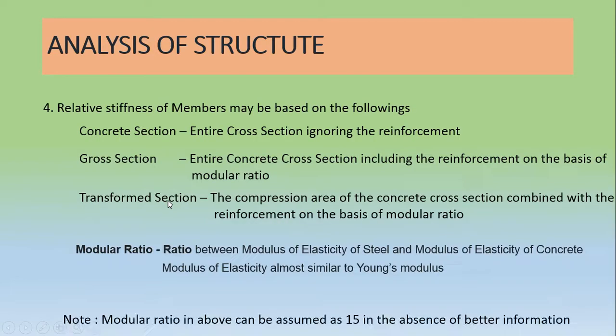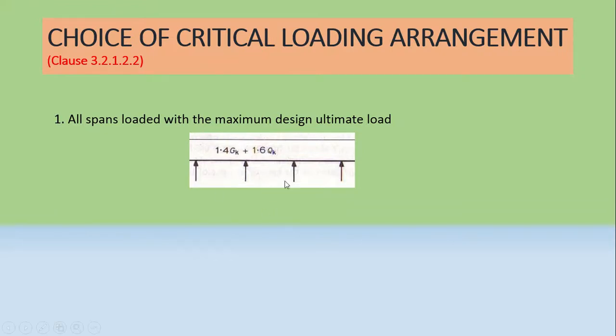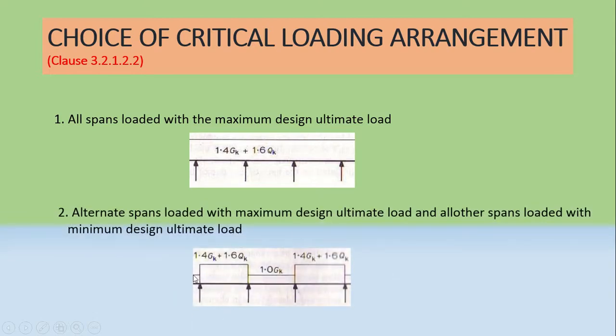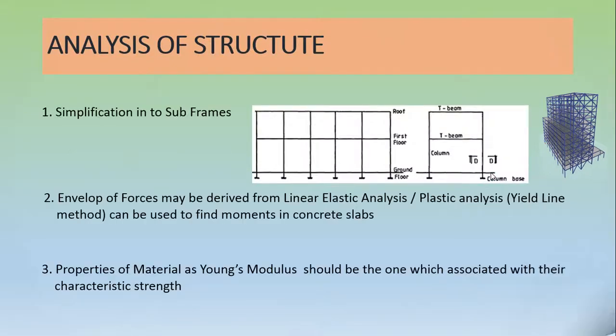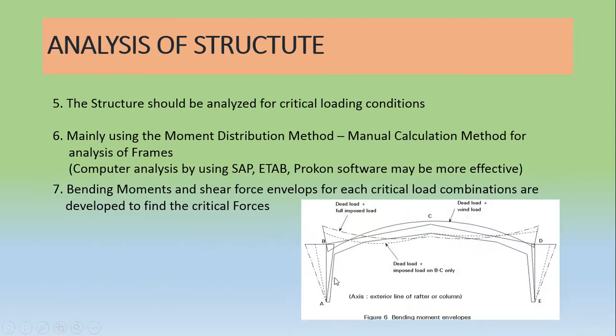Earlier I showed you this beam, and we can draw a bending moment diagram on the same beam, and for another load combination you can draw another bending moment diagram on the same beam section. So here we consider this frame. Let's think that one bending moment diagram is where we have considered dead and full imposed loads, dead load plus full imposed load.